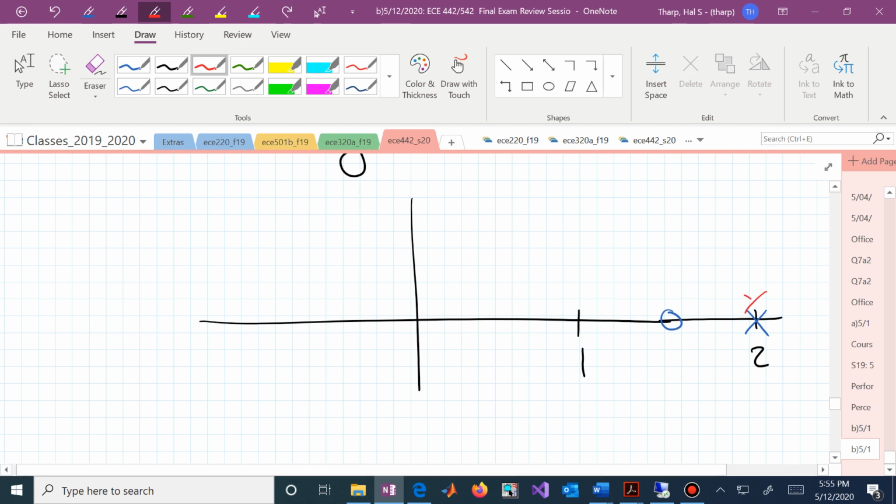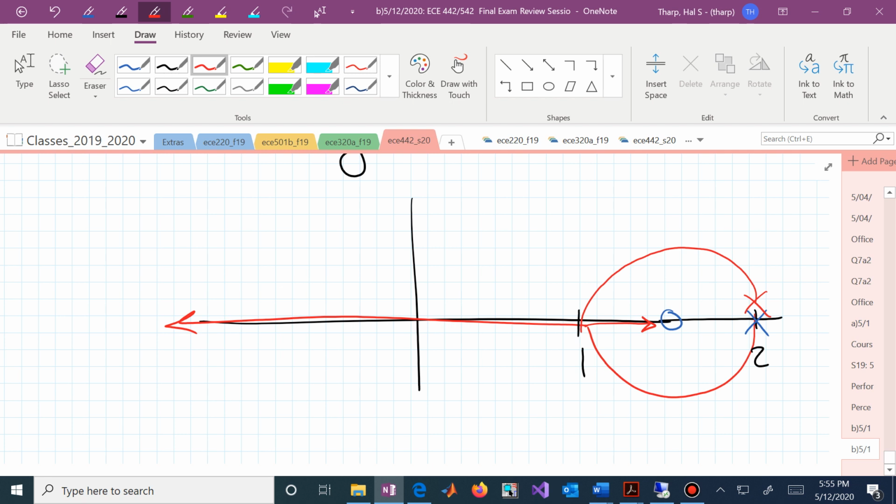If we did 2 poles to the right of a 0, now we know we have a circle. Oh, but look what happens. The radius of that circle is exactly 1/2, so I'll never get both branches of my root locus simultaneously inside the unit circle. So that pole won't work, but I'm on the right path. I hope you can see that.